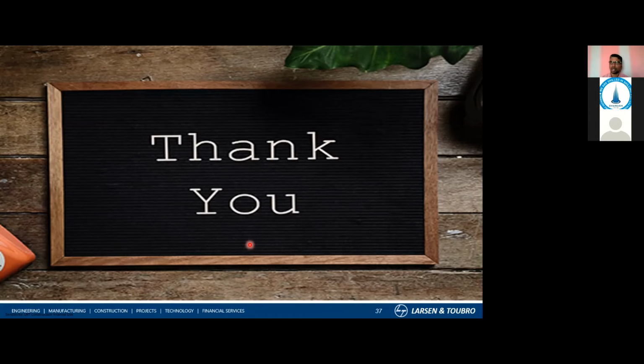Some facility you are keeping, for example a shower is being placed. If there is a shower, you need at least some minimum pressure to reach that shower to operate. If you have any limitation with keeping this 2 meters, for example it won't look good aesthetically, then probably you can look for a lower height, which is also accepted, but you should go with some amount of boosting system for the pressure for the low level zones. So that way only you have to fix it.